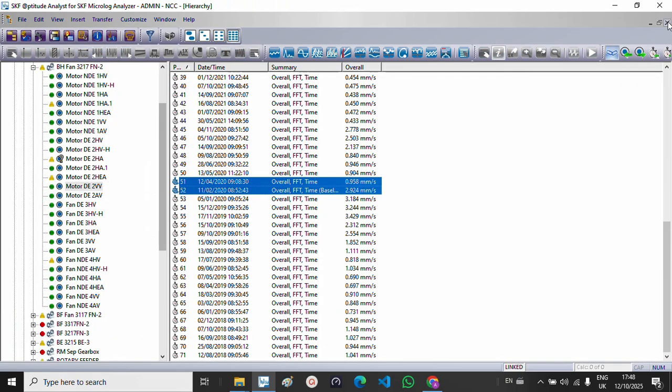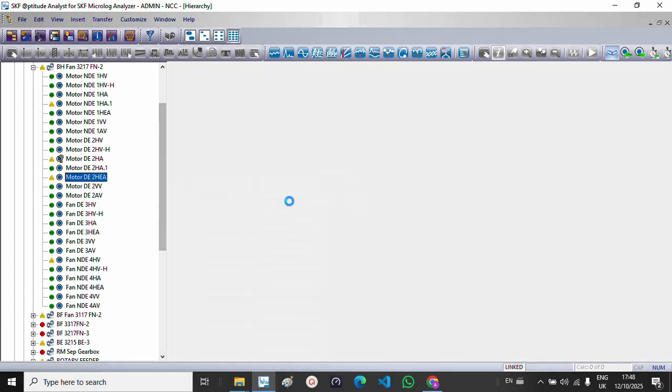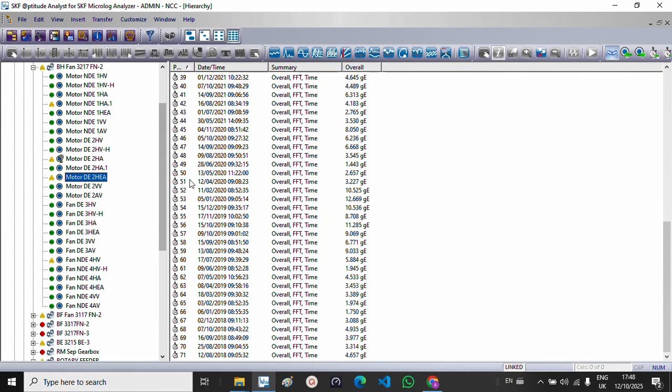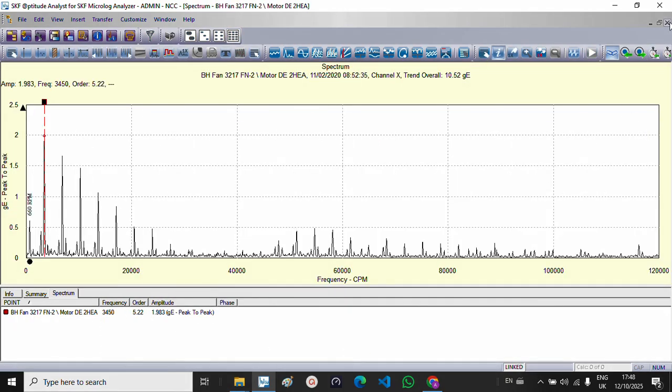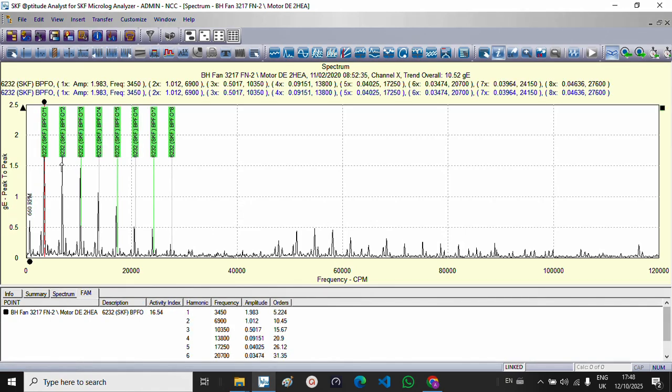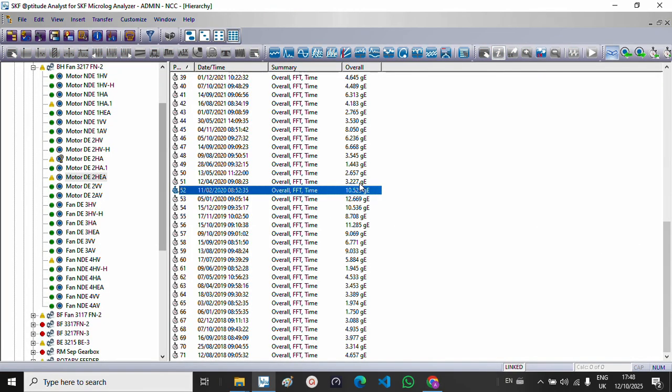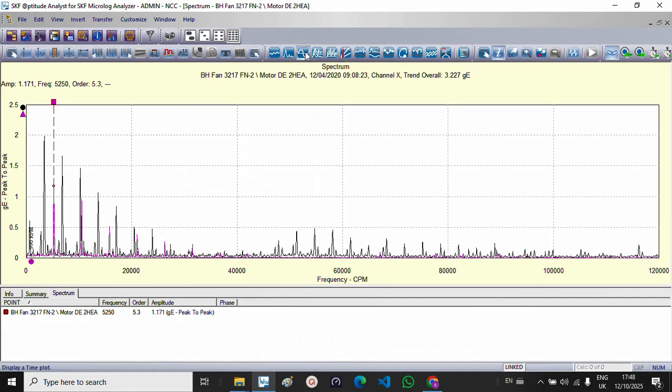Now we check for 1 point only. Can we check the gE, the envelope acceleration, that we see here as it was before with the faulty bearing? It was high. When we changed it, it decreased. And see here, oh, it is a big problem as we see here. Oh, it is clearly an outer race problem, and we can make the comparison between them.